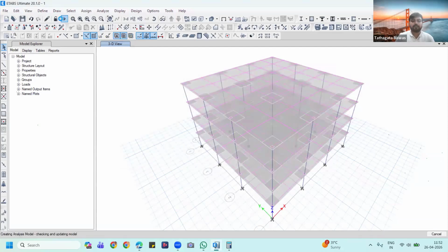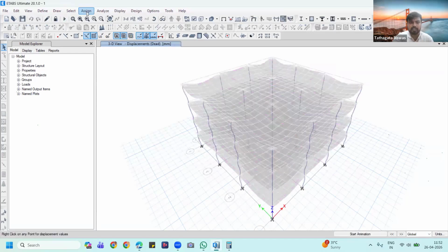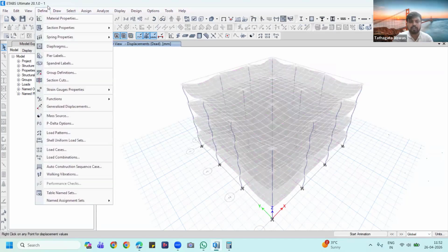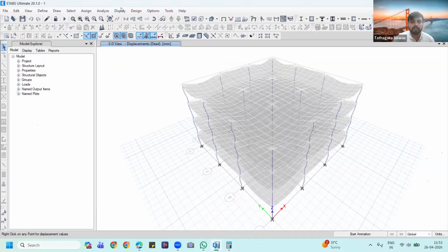Now you will be getting the dynamic base shear, which will always be lesser than the static base shear because of the infill panel, which I started this session with. Since that is not considered in dynamic, right? In dynamic, what parameters have we given? We have given the soil type, zone factor, everything, but we have not given any time period. The time period is considered based upon the model that we have. In this model, there is no infill panel, no wall, nothing. We have considered beam, column, slab, shear wall. That's it. But walls would also be there. That is not considered because of that only.